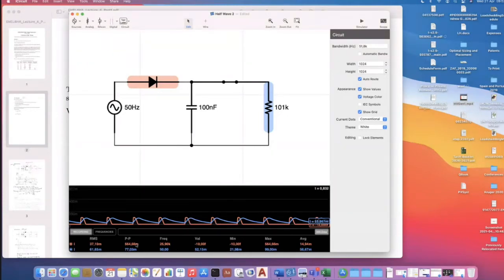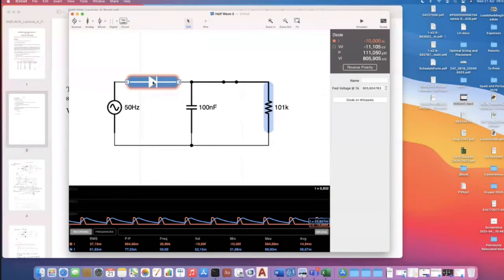So it's important to know that, because these components have set ratings. You get a 10 kV or 20 kV diode, but it'll only be able to handle 5 milliamps. If you look down here, we're actually higher than that already. So that's a problem.